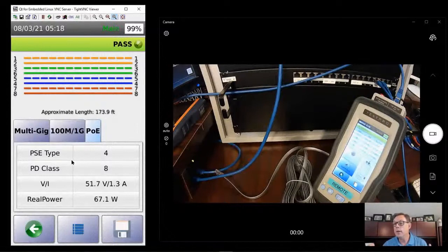You can actually have some more value-added documentation that your network is in good shape, what your PoE performance looks like, what your SNR values are, because a lot of things change from the time that you install it to the time everything is turned up, everything is in the building. Other equipment not related to your data networks might be in the building that's generating noise. Any number of things can impact that performance. So this would be the other test beyond troubleshooting the PoE.